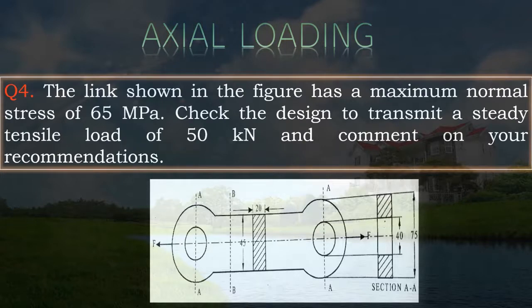Let us solve one more numerical on axial loading. The link shown in the figure has a maximum normal stress of 65 megapascals. Check the design to transmit a steady tensile load of 50 kilonewtons and comment on your recommendations. He has given a link as shown in the figure. He is asking us to check the design.